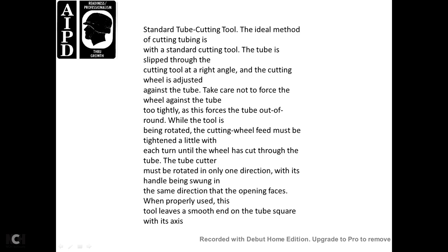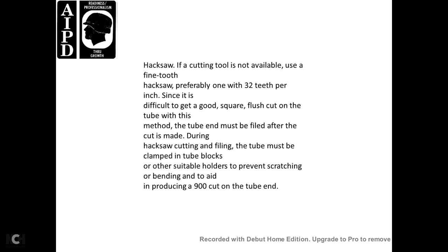The tube cutter must be rotated in one direction only. It is handled and swung in the same direction. When properly used, the cutter leaves the smooth end of the tube square with its axis.